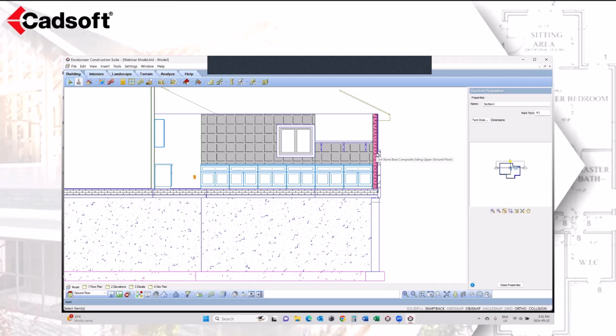So it understands within the solid piece of this stud component that's in the wall that it has that hatch pattern associated to it. So by having those section views, now you don't have to do that extra work of applying those hatch patterns when you transfer your model into the working drawings in a section view. As long as the component itself has that hatch pattern attached to it, because it's now a solid and we cut through it, it will show that hatch pattern for you.